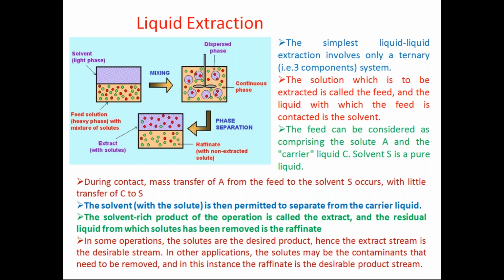You can name that solute, the active component, which will be exchanged between these two phases. And the third one which you are adding for the purpose of separation is organic solvent. So that is called the extracting solvent. Feed solvent, extracting solvent, and the solute which is getting distributed among these two phases. So this terminology is used.